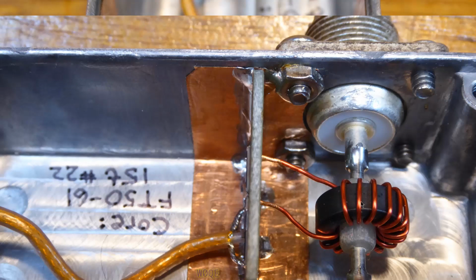We could have, and I should have thought about this, I could have moved this circuit board in, notched it a little bit where the nuts are here, moved it closer, and used these wires to hold this toroid by itself. I could have dispensed with the plastic and just put a bare wire through the center. That would have given me less capacitance. As you can see here, I did not run the shield through here and back on the other side. This is a fairly short distance. I did not run the shield through here.